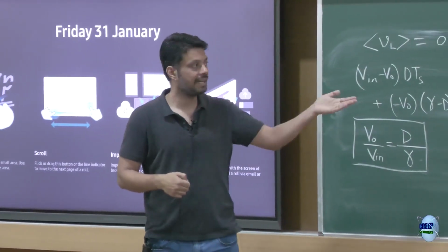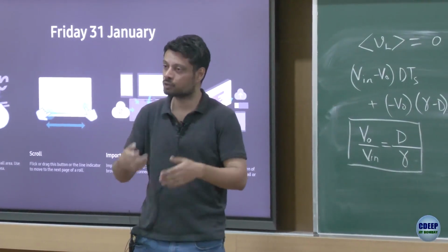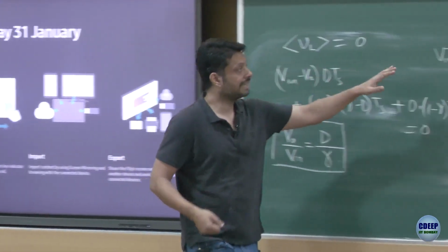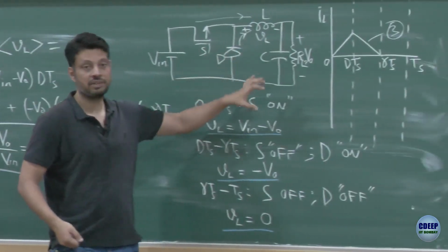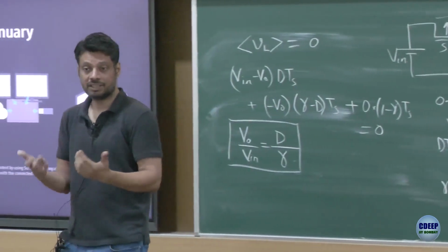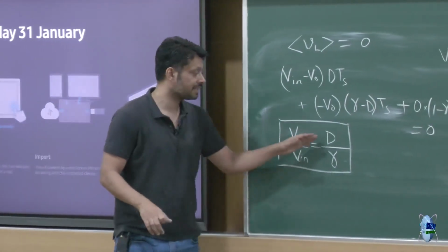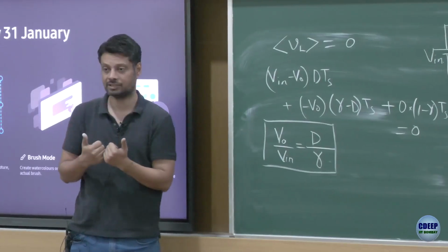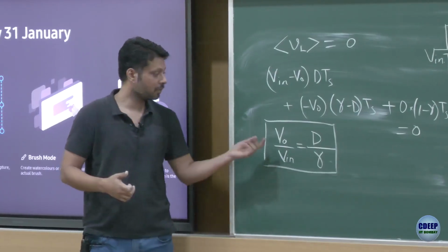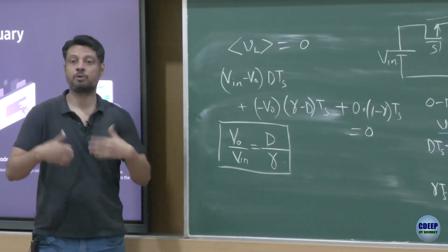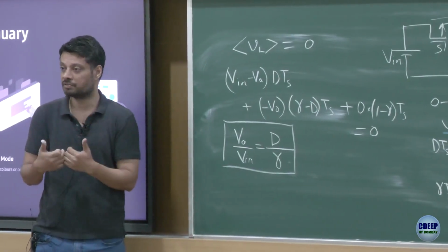And therefore, in reality, all these converters have to have a closed loop kind of operation, where the duty cycle gets adjusted based on observation of the output voltage, right. So if you see output voltage becoming 60, you adjust the duty cycle. The relationship is still the same, that if you reduce the duty, the output voltage comes down, thank God, that doesn't change. So it's still the same relationship, but the factors will keep on changing. So if your output voltage goes to 60, you bring it down to 50, right.